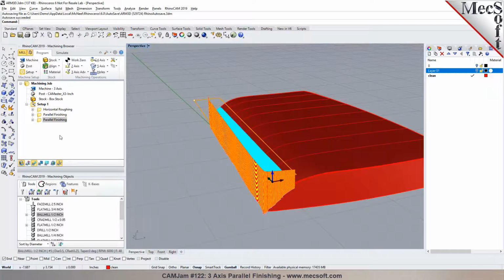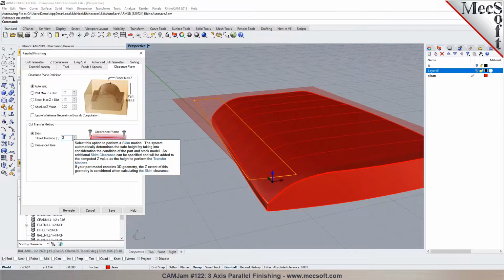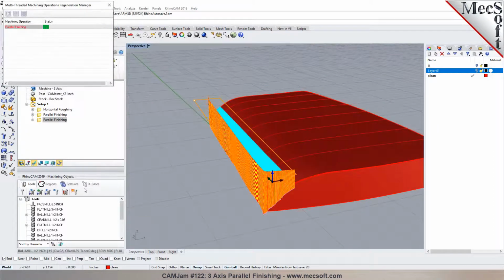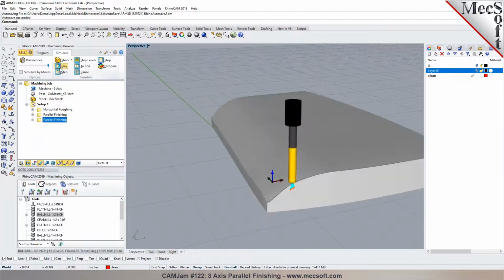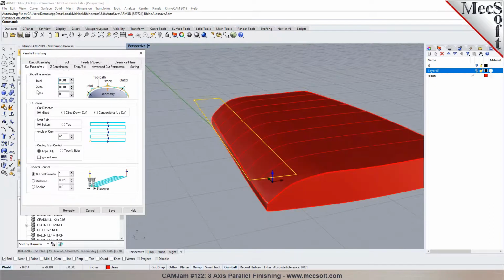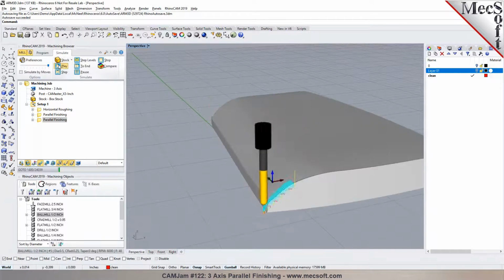as you notice. And you can change how you want the tool to retract. So that'll give you a toolpath with fewer retracts in here. So now you have another final finish operation that you can create. And you can always change the angle of cut, the step overs, everything can be controlled. So that gives you a much finer finish over there. So you have precise control.